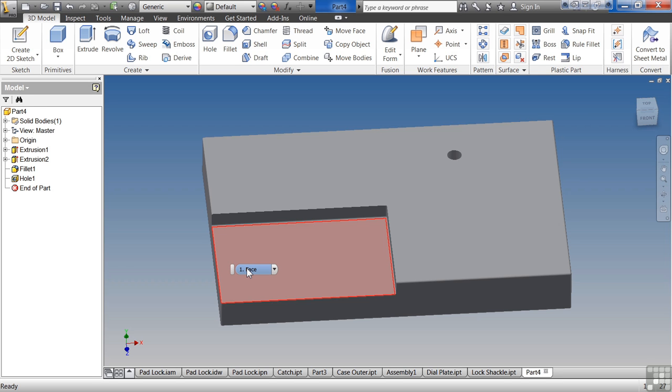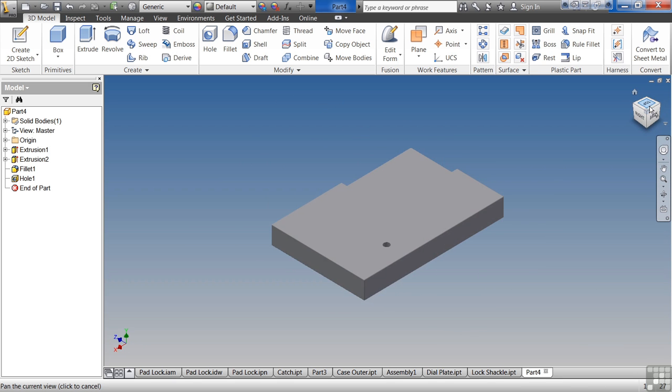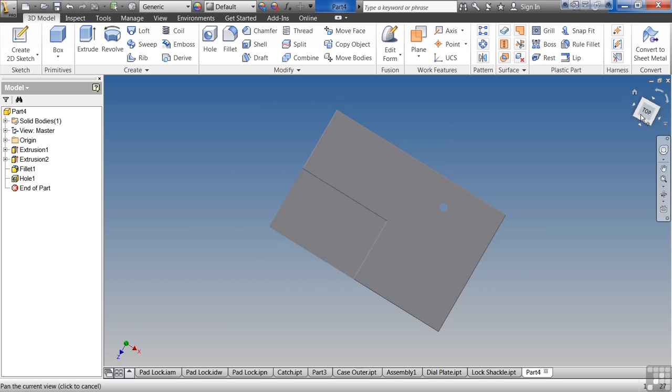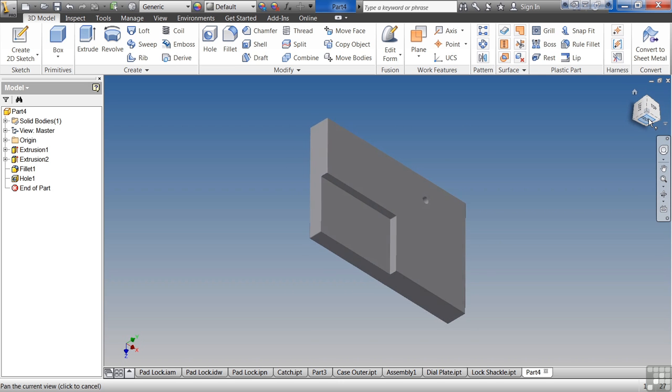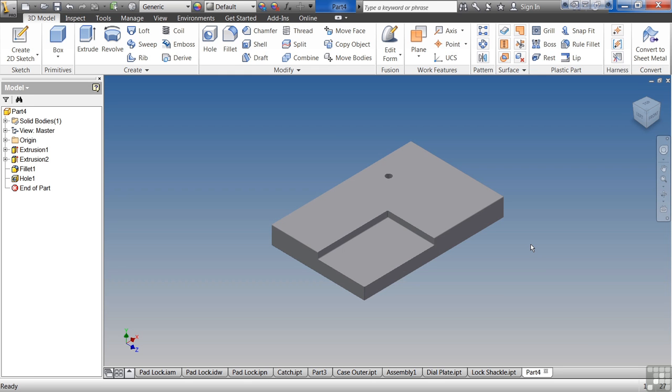And remember that our base part was a big square, big rectangle. So it was very easy to determine what it was going to be. You can play with zooming around a little bit here and look at your first part and see how Inventor plays with it and works and gives you what you need. Remember that the largest goes first, second largest next, order of importance. Size does matter in Inventor, so you start out with the largest object and work your way down, the hole being the smallest, so I'd place it last.